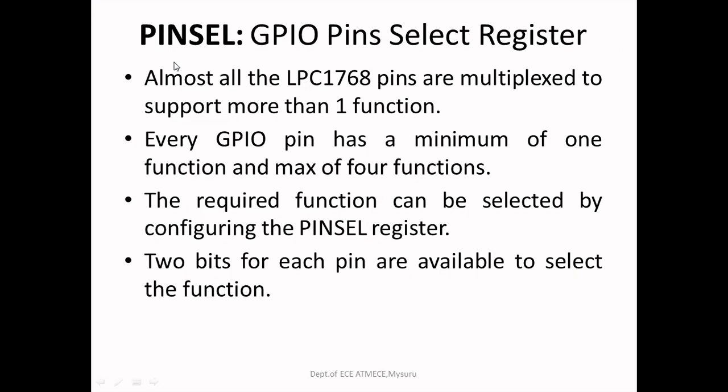The necessity of the pin selection register is that almost all the LPC1768 pins are multiplexed. Multiplexed means each pin can perform more than one function, that is, a minimum of one function and a maximum of 4 functions. Pin multiplexing is a scheme adopted to reduce the number of pins in the controller. Therefore, the required function can be selected by using the pin selection register, which is used to select a function of a particular pin because each pin is multiplexed.